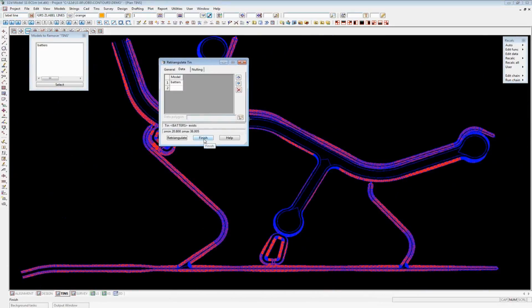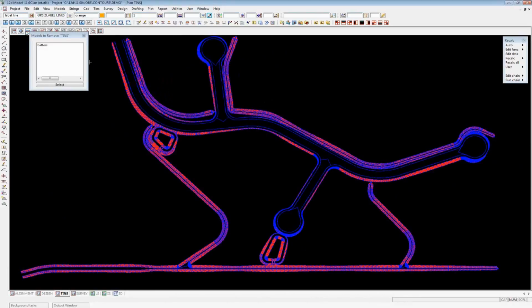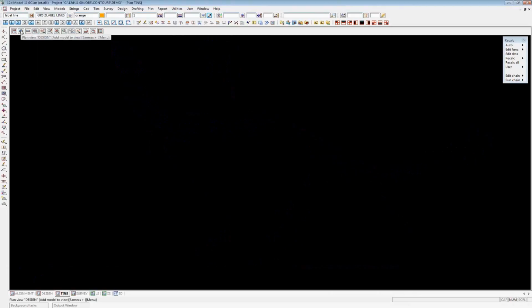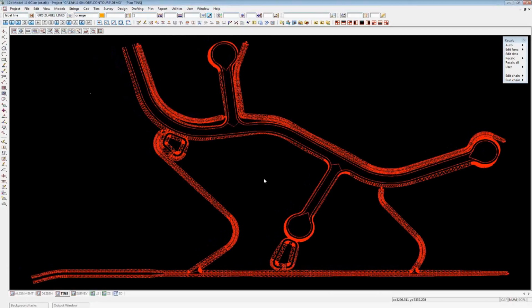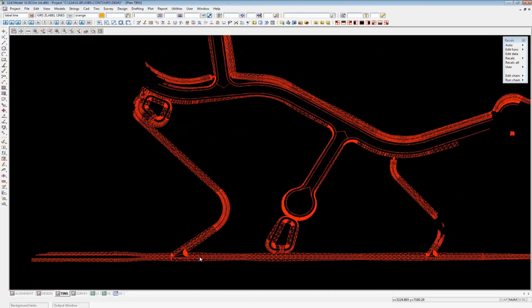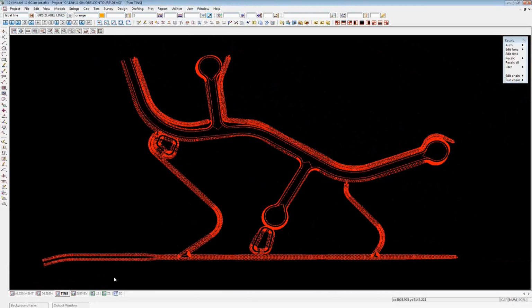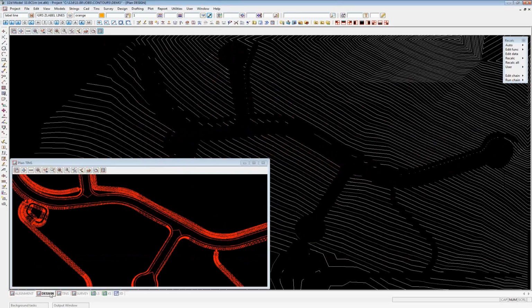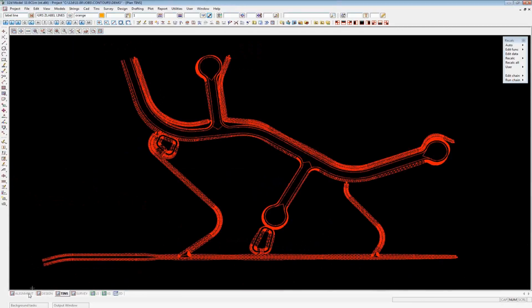You just need to specify this data and triangulate it, and it's going to create this model called tin batters. Okay, and that's just a triangulation of that model. Okay, and this represents where the design tin is steep, if you like. Okay, and we can use that now to mask out elements of our design from the contours.